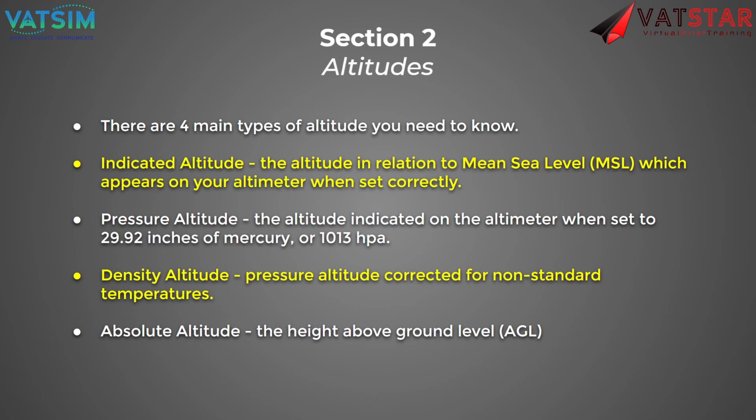When they're saying pressure altitude, that is your altitude in relation to what they call the standard datum plane, which is basically the level where the air pressure is 29.92 inches of mercury. I have a little graph in a section that's going to make it easier to understand.